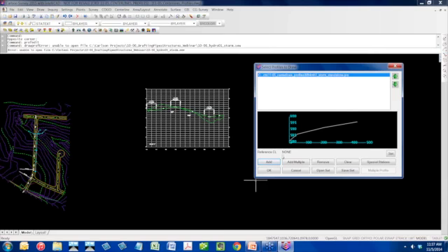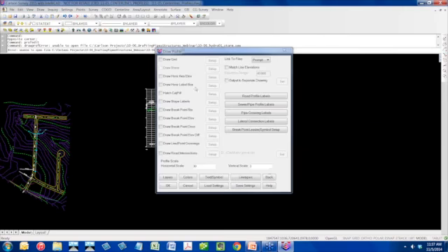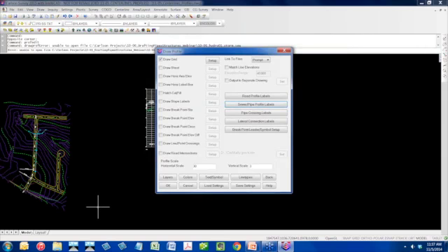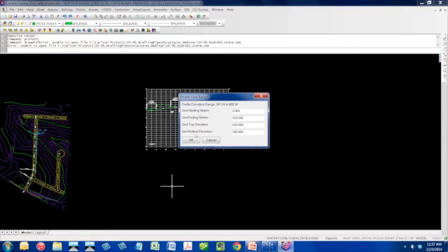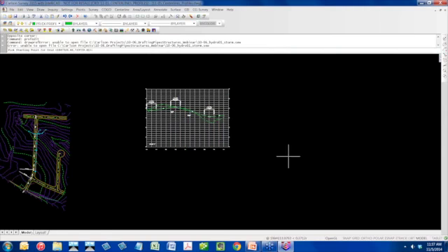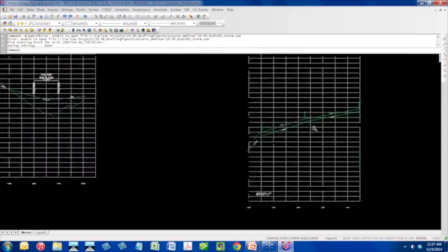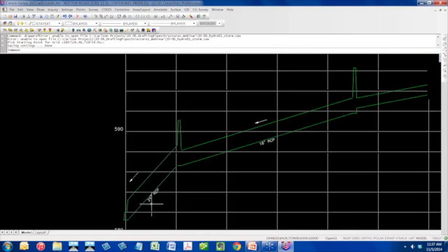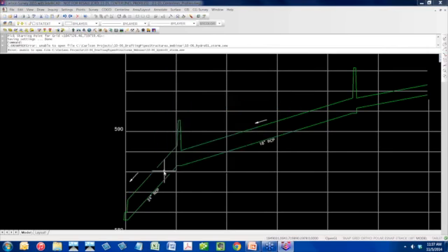So I've added in my profile name. I'm going to turn draw grid back on. The sewer pipe profile labels are pretty ugly right now. Let's just draw it once, and then we'll go in and make a couple changes. Pick OK, and grid bottom, go with that. All right, so I got some pretty ugly pipes, manholes, and labels. So let me hit my enter key and repeat that command. Let's go in and make just a few changes.